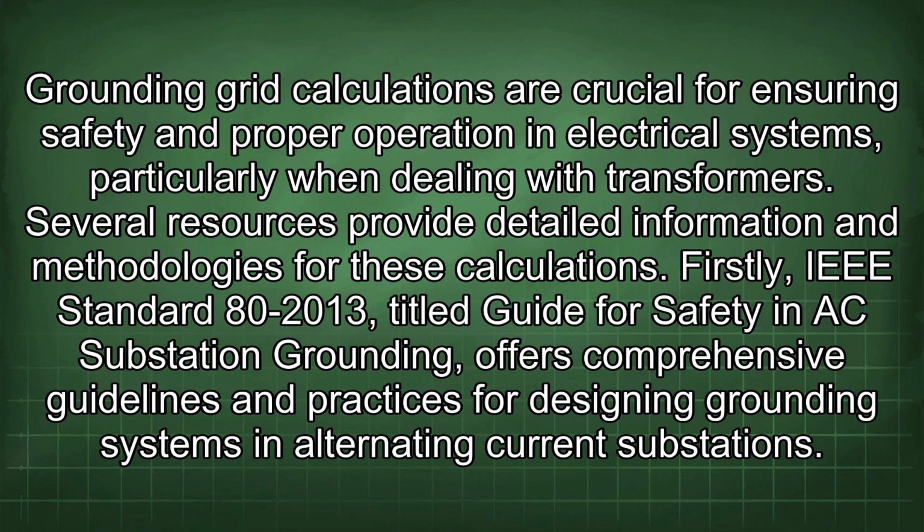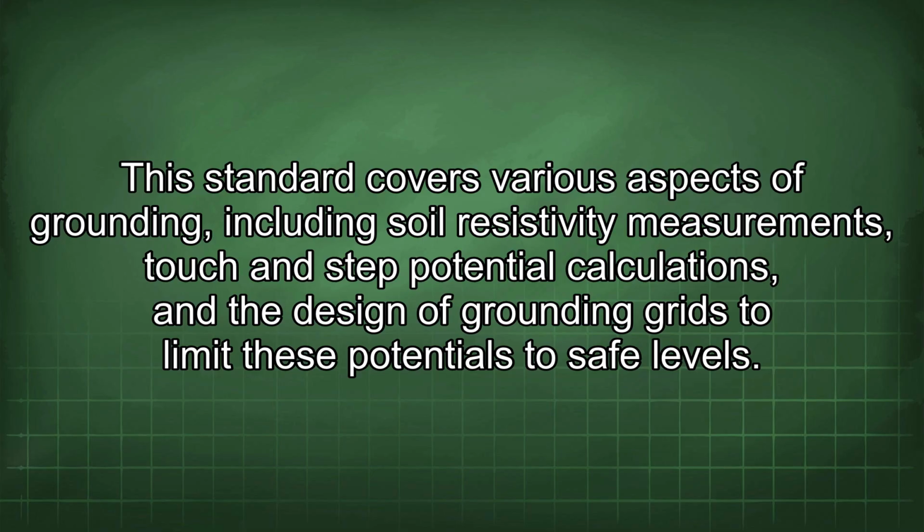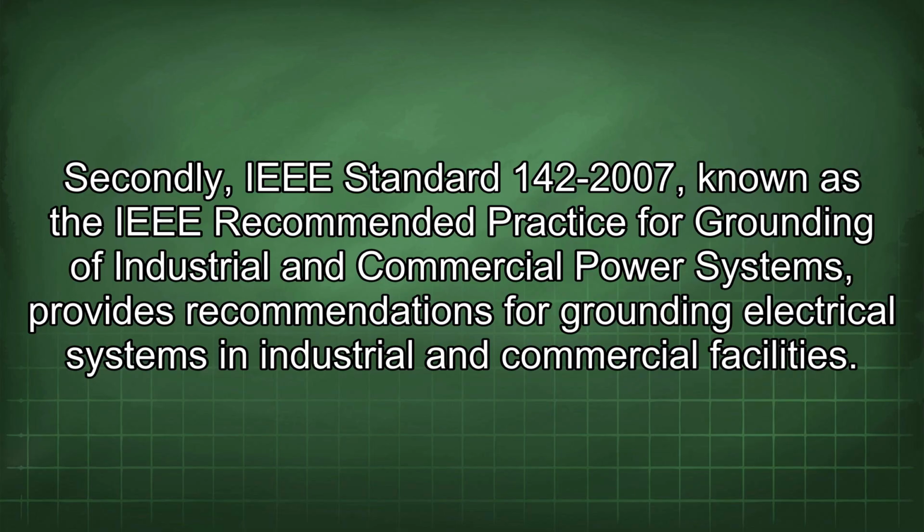systems in alternating current substations. This standard covers various aspects of grounding, including soil resistivity measurements, touch and step potential calculations, and the design of grounding grids to limit these potentials to safe levels. Secondly, IEEE Standard